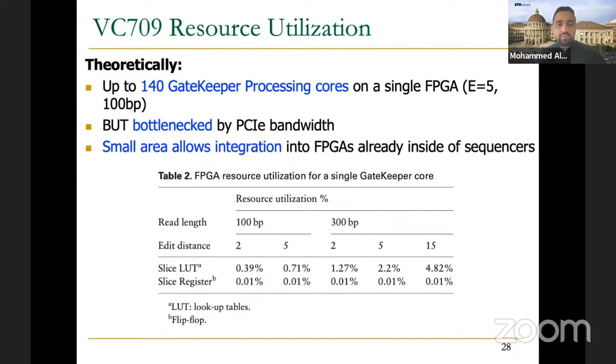gates in parallel. Sometimes you cannot apply the VCC or the ground to a large number of gates, and that's specified or controlled by the total critical path or the worst delay in any of the input signals, for example. So you may need to use pipelining techniques to reduce this critical path, for example, or you reduce the number of replications. These are all challenges when you implement a parallelized algorithm in FPGA, or you would like to fully utilize all resources you have in the FPGA.